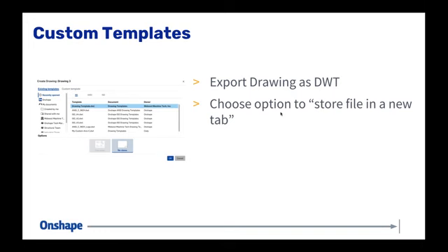It meant that if you're trying to do min-max dimensions of the outside or the inside of arcs, it could be troublesome, right? It could be somewhat difficult. But now just grab that drag point, just as I did with the arrow, grab that drag point of the dimension, and you should see the outside of arcs as a selectable option, right?